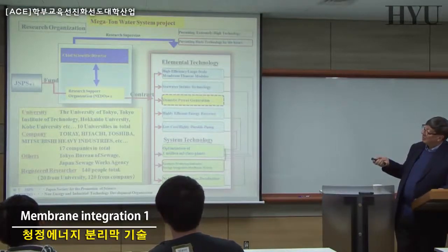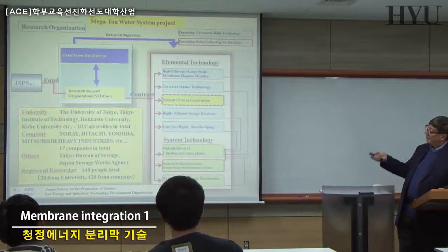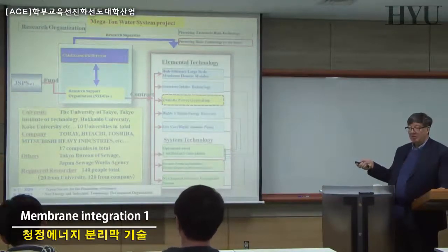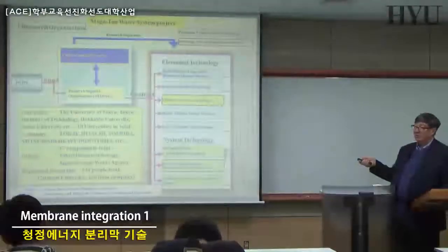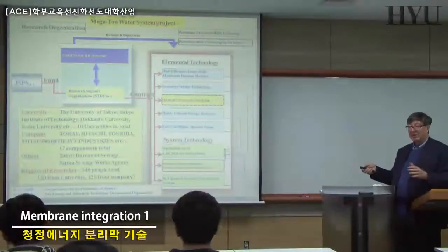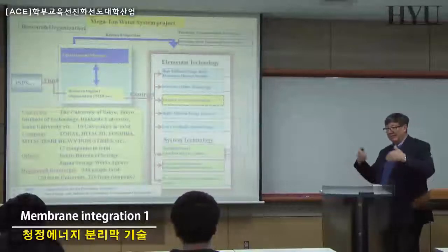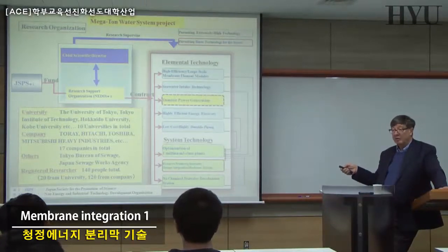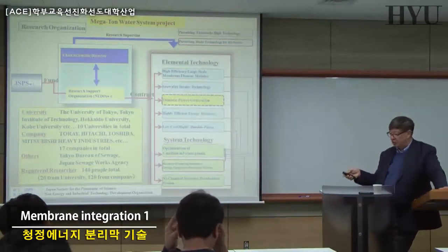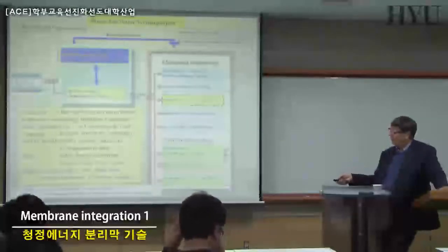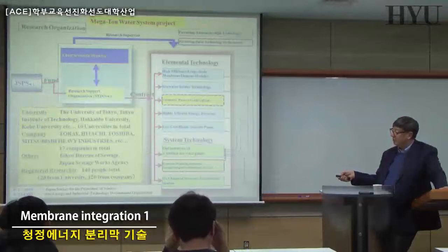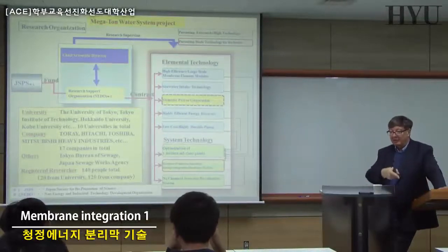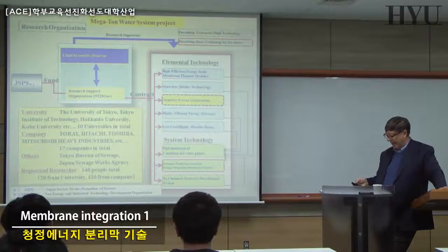And you can see here Megaton, and you can find more references in the literature, but if you look at the technology they were introducing, you see osmotic power generation is already part of it. So PRO was already in the logic of Megaton. Megaton now is close. Now they are making the industrialization of this, considering not only production of fresh water but also osmotic power generation. And all these plants are optimized for the 1 million cubic meter class plus. They make a new class of plants, 100% bigger than the one installed, that are starting to operate now, basically.